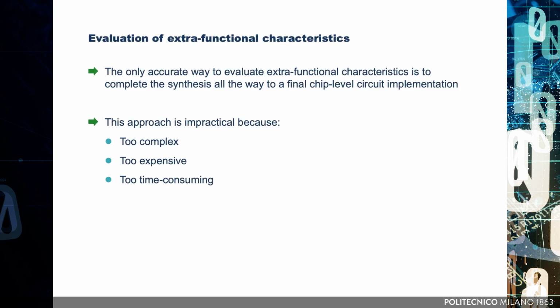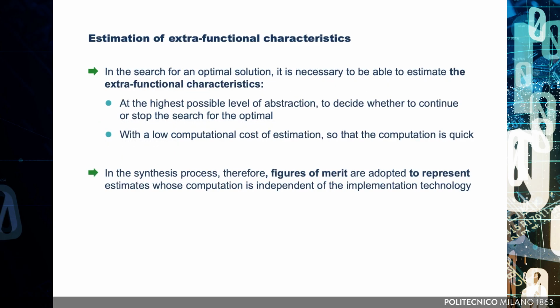However, this is practically unfeasible because it is too complex, too expensive, and too time-consuming in terms of development time. Since we cannot build the chip just to evaluate the characteristics of a circuit, and since we also want to keep the logic synthesis process independent of the later design stages, we rely on methods to estimate the extra-functional characteristics. These estimates help guide the optimization process during synthesis, allowing us to identify the best possible solution.